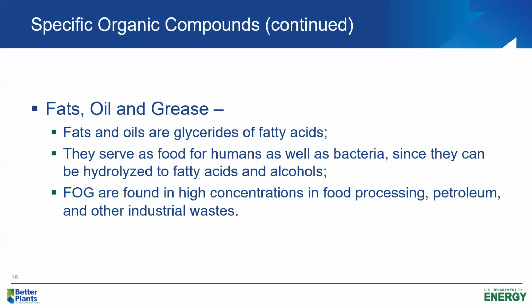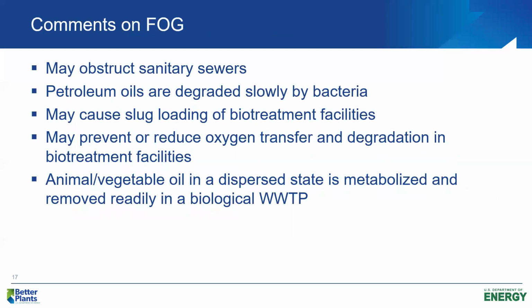Petroleum oil and grease is not nearly as biodegradable as animal vegetable oil and grease, and sometimes it can create problems for us. Animal vegetable oil and grease is readily metabolized by the bacteria, while petroleum-based oil and grease is very slowly degraded by bacteria. And so we're always concerned about the oil and grease content coming into the treatment plant.